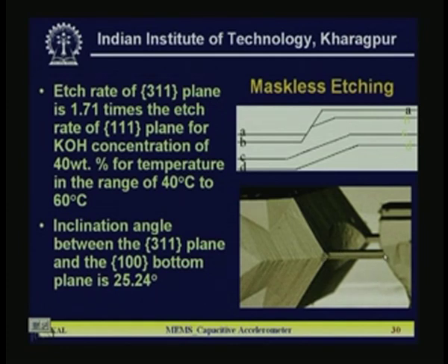Earlier, in the piezoresistance case, this kind of flexure was not coming into the picture, because there we diffused piezoresistances on the surface of the single crystal silicon. So you cannot make the flexure at the middle of the cross section.